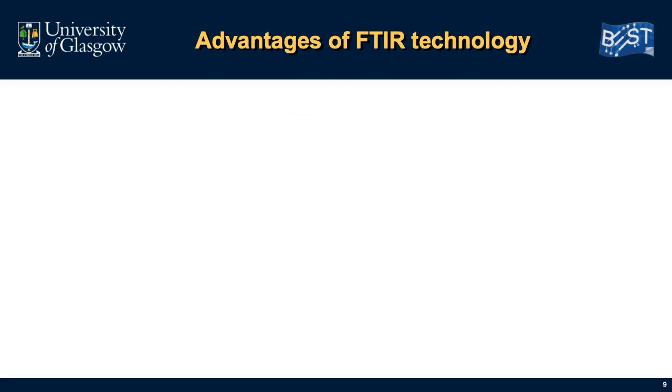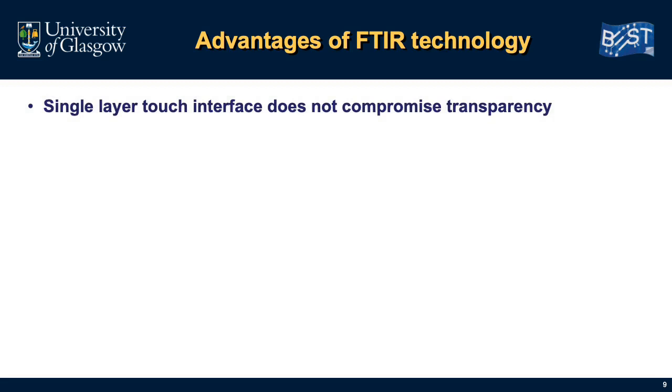When considering the use of FTIR for 3D touch surfaces, and with the interactive pseudo-holographic display application in mind, the technology does have some advantages. Compared to other sensing technologies, such as resistive or capacitive, the single-layer interface of the FTIR does not compromise transparency, something that is important for this type of displays.